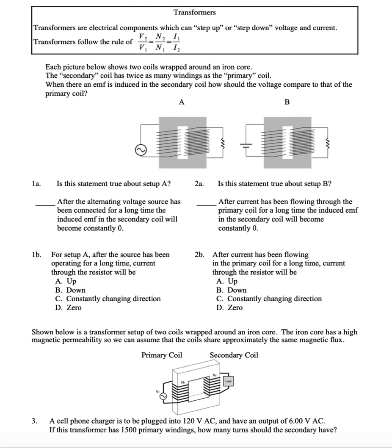One of the most important formulas involved is that the voltage of a coil is proportional to the number of turns in that coil. Shown here are two coils wrapped around an iron core. The iron core allows the magnetic field created by one coil to easily flow through the other coil. So the magnetic flux created by one of the coils will also be felt by the other coil. But the more turns a coil has, the more that voltage gets magnified.